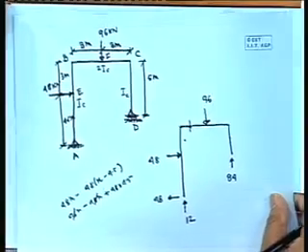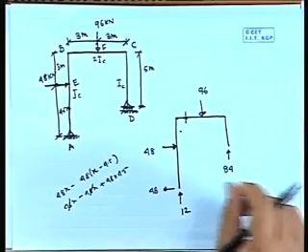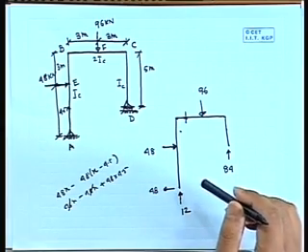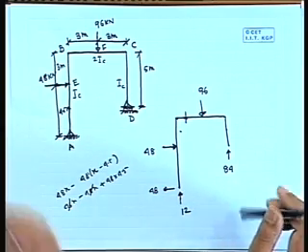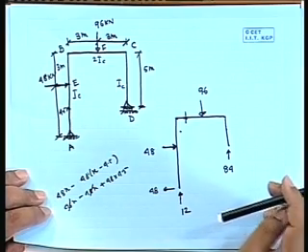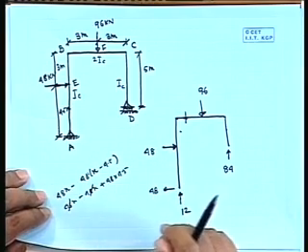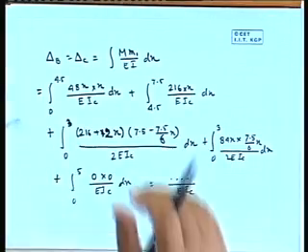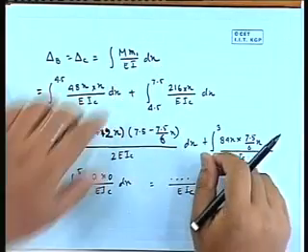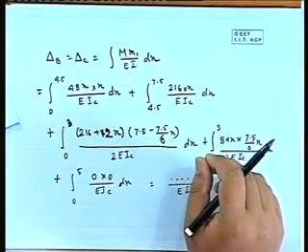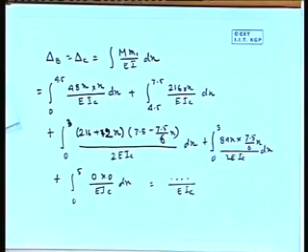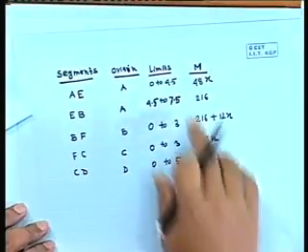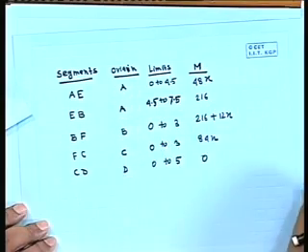Say this problem where you want to find out the slope. So the 96 kilonewton doesn't play any role. 96 kilonewton will play a role in finding out the capital M, right. So it has 2 components, M and small m. This capital M is due to the actual load. So this table we have generated, it is 48 into x.